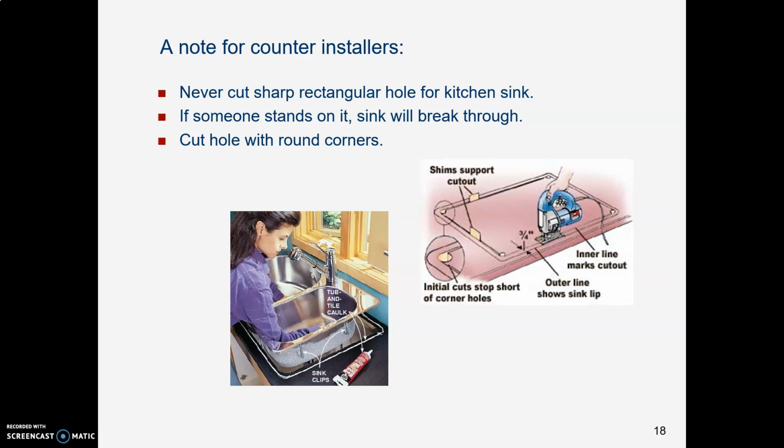Here's a sink installer. She cuts rounded corners in the opening in the countertop. If she were to cut a sharp corner, well, that is a recipe for a stress concentration, especially if somebody does something like use the counter as a stepladder and stand on it, the thing will just crack.